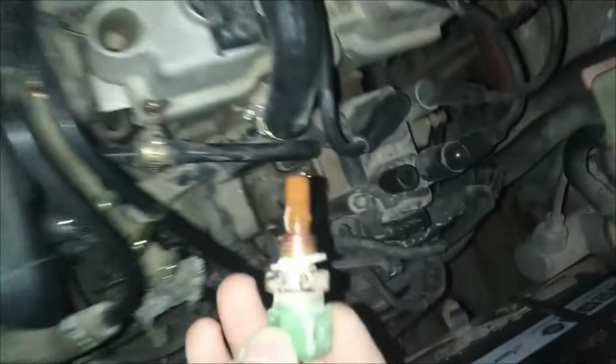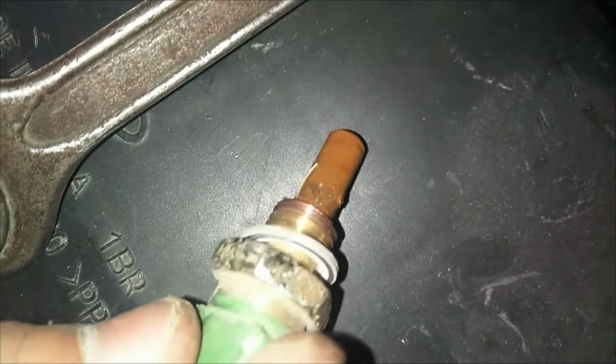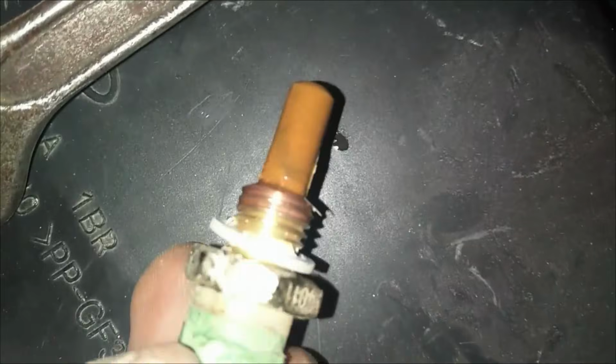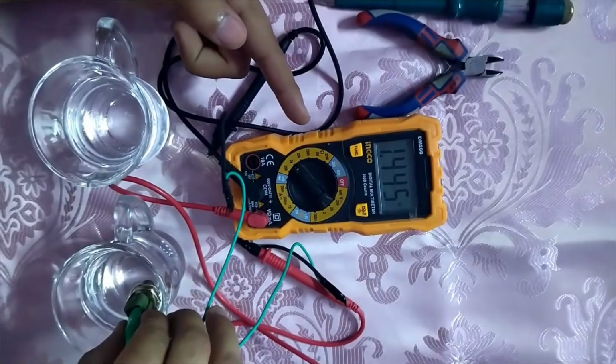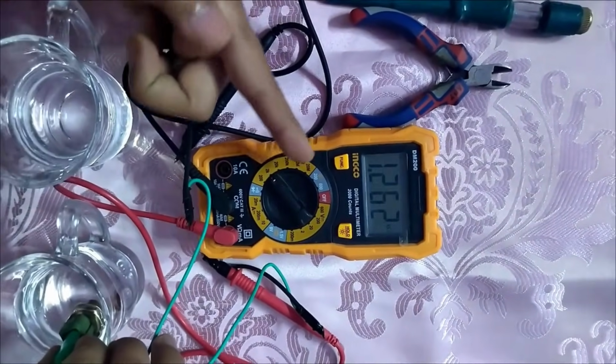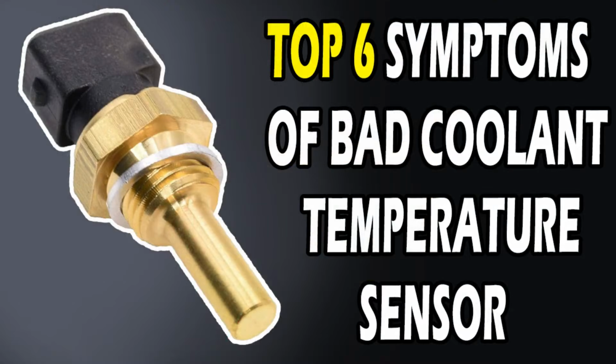However, if the coolant temperature sensor fails and provides a constant low temperature reading, the ECU will assume the engine is always cold. As a result, it will continuously inject excessive fuel in an attempt to raise engine temperature, leading to significantly increased fuel consumption. To confirm a faulty coolant temperature sensor, you must monitor its readings using a diagnostic scan tool. We previously covered all coolant temperature sensor failure symptoms in a dedicated video. Link in the description below.